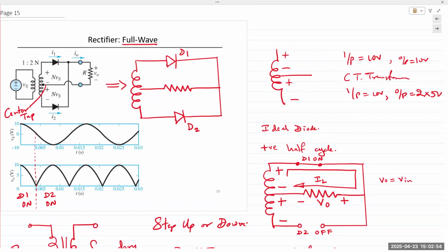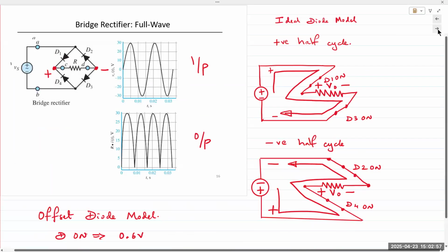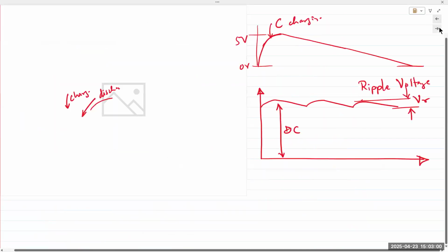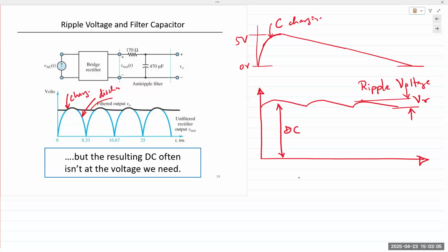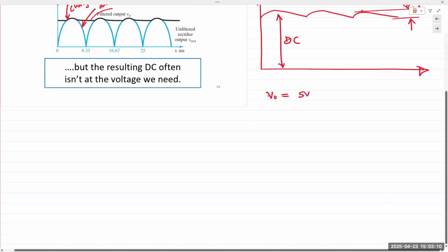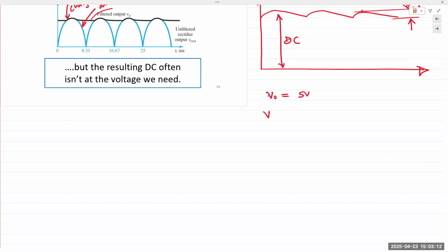That's true. So the question being asked is, as a circuit designer, how do you account for that? Well, you work backwards. So if we want V out to be, let's say, 5 volts, then I need my Zener diode VZ input to be at least greater than, even at the lowest end, like 7, 8, just to be safe, like 8 or 9 volts. So like 9 volts perhaps, maybe even 10, doesn't really matter.